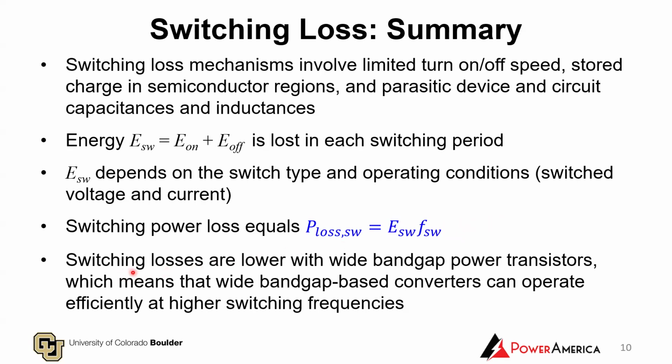One thing that we want to note here immediately is that the switching losses are lower with wide bandgap power transistors, which means that wide bandgap based converters can operate efficiently at higher switching frequencies, which can again result in smaller size of the power converters.